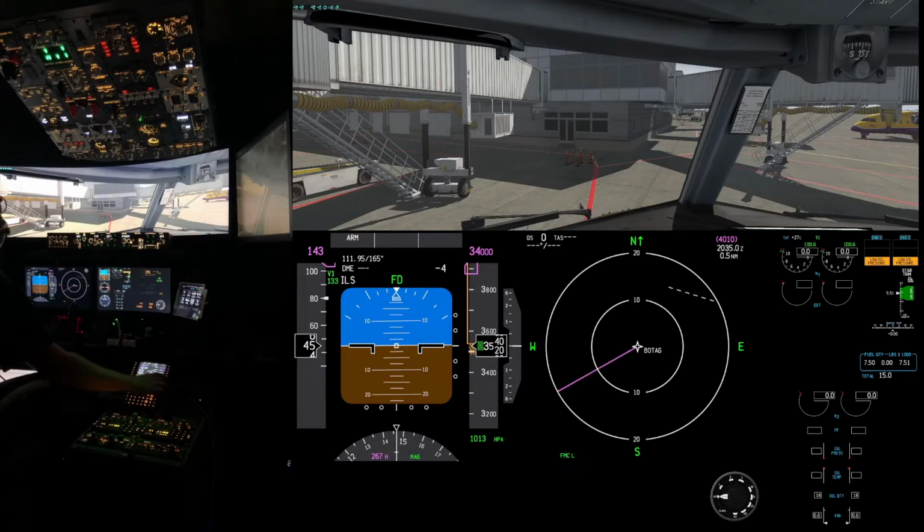My first waypoint with vectors from air traffic control is BOTAG, then Booth, Stave, and then we're starting to get into the approach procedure for 8 right, and it takes you to Vinlo, with then vectors based on air traffic control's direction to bubble down to 8 right. So that looks all good.